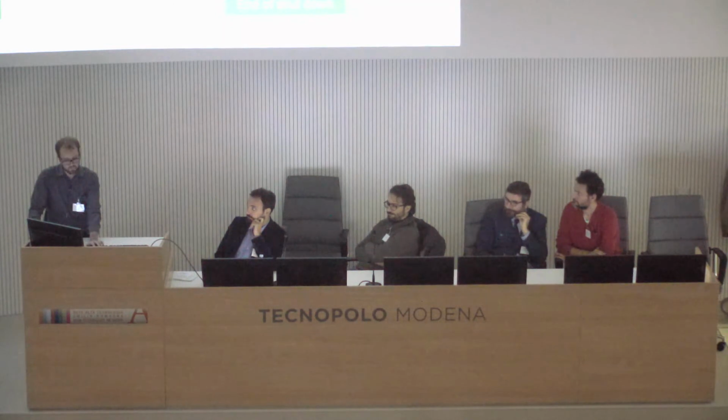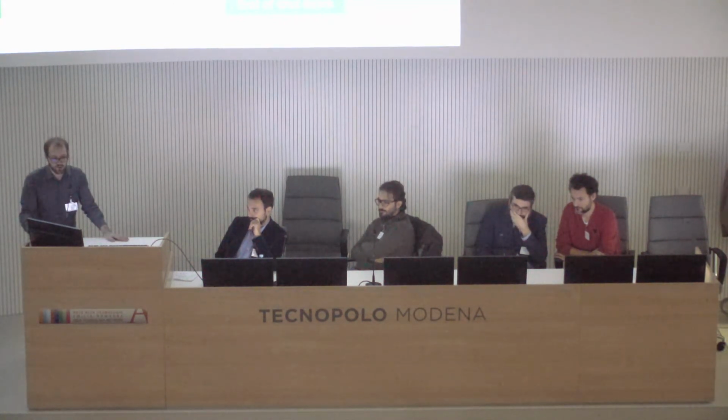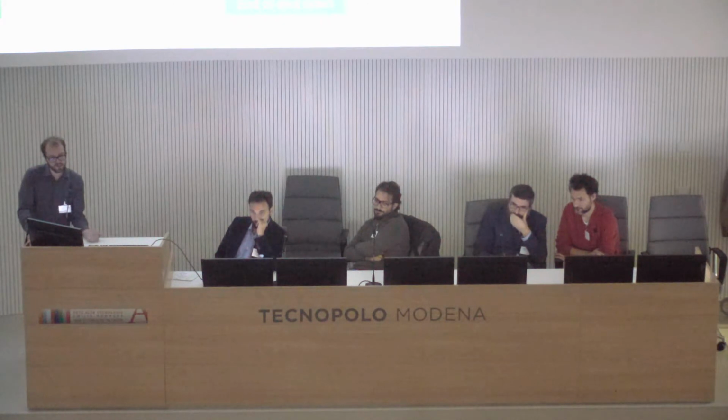So there's no crack yet, but we are already quite confident that our model is not so bad because it can reproduce a little bit of the stress state that happens locally. And if we look more carefully, at the end of the beginning, we see there is a very, very strong gradient of the stress state: inside there is tension, but on the outside there is compression. And then it's the other way around afterwards.